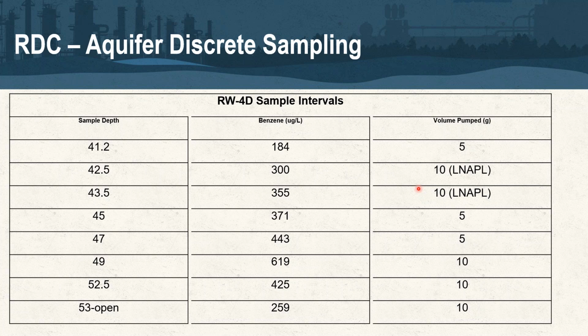And seeing also the spacing between these particular intervals, without that 18-inch short interval packer, we would not be able to see this kind of resolution and know where that NAPL is specifically coming from. Having that tool available allows us to walk up and down that borehole at tighter intervals if need be, to get more detail and higher resolution of those particular locations within that borehole and what's going on. Next slide, please.